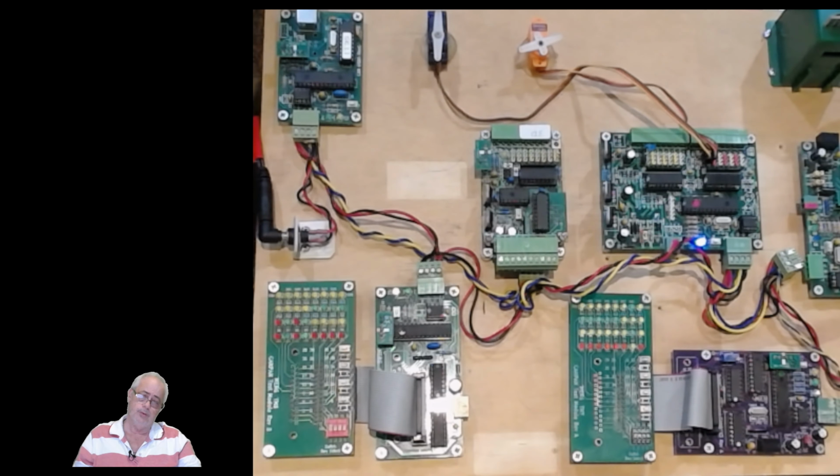The movement of the point will generate feedback from the start, the middle, and the end. And I'll use those feedbacks to control the LEDs on the panel and the output for the frog polarity. So probably at this stage, it wouldn't be a bad thing to make the switch make the point move. So let's do that.